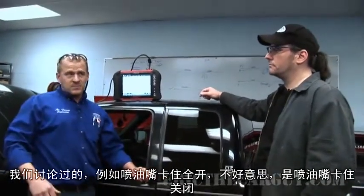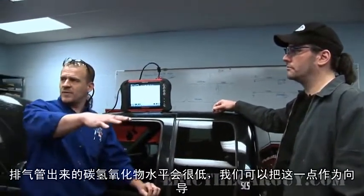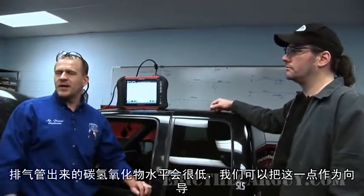Like a stuck closed fuel injector, for example. Our hydrocarbon levels will be very low coming out of the tailpipe, so we can use that as a guide. We can scope the injectors, we can do relative compression tests, we can look at secondary ignition.